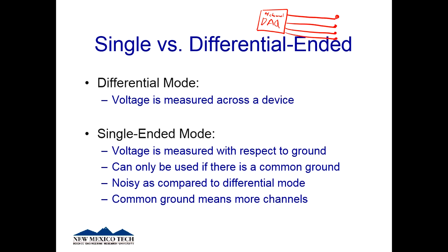One of them is tied to the channel, and then we assume there's a ground. That's basically the other end of each of these sensors. We'll talk about grounding, I think, maybe next week. But the bottom line is, that's one configuration. That's single-ended, SE.